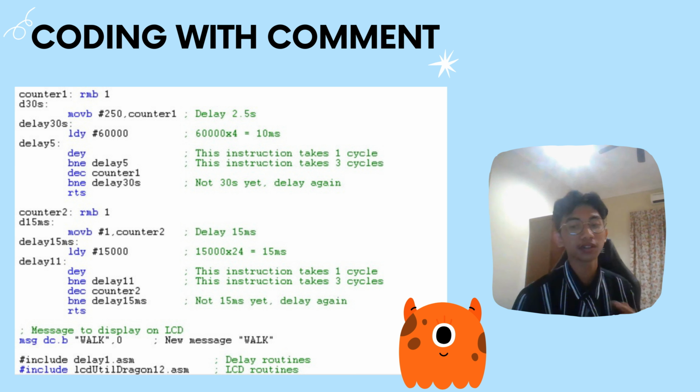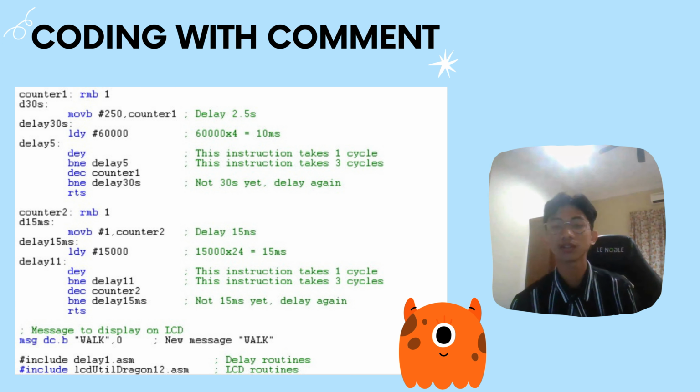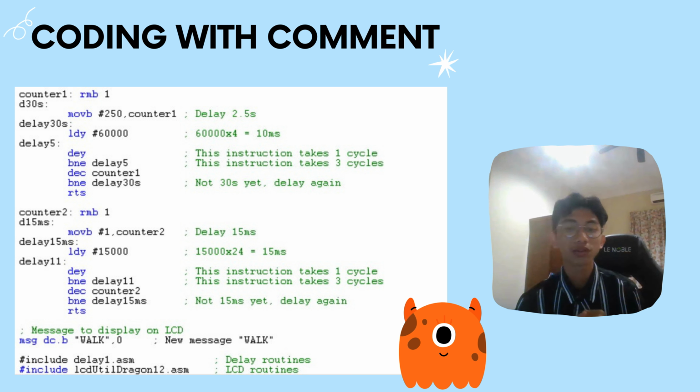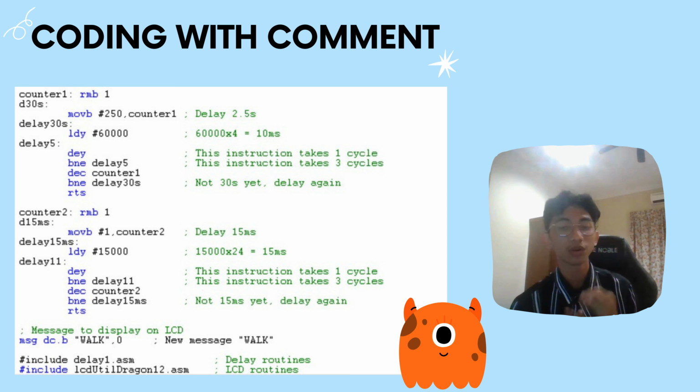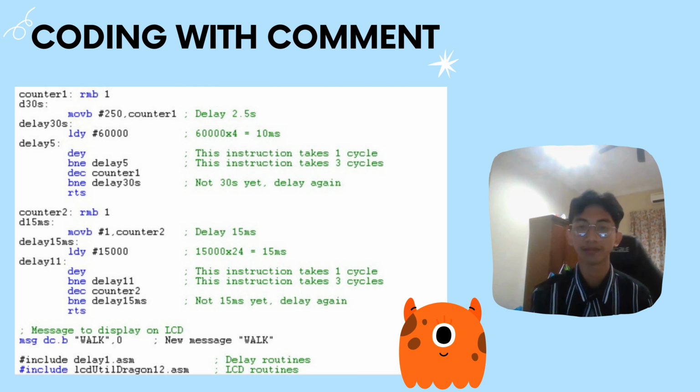The coding after the 30-second delay continues by implementing two delay subroutines: first is D30 second for a 30-second delay using nested loops, and D15 millisecond for a 15 millisecond delay, while also defining an LCD message "walk" to be displayed. So for the message to display on the LCD, we included delay 1.asm for delay routines and also included LCD Dragon 12.asm for LCD routines.